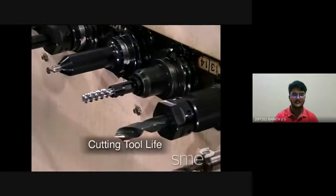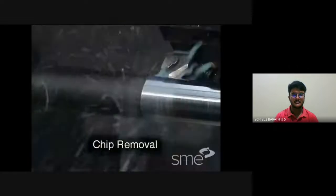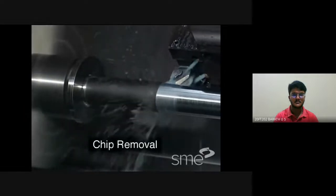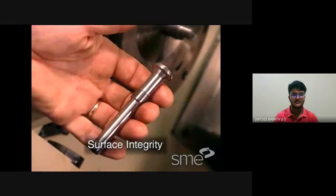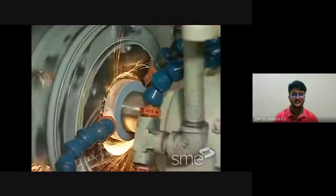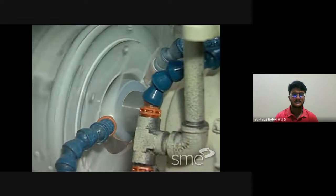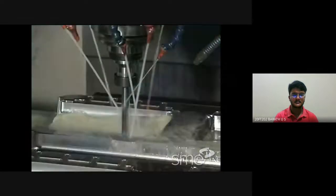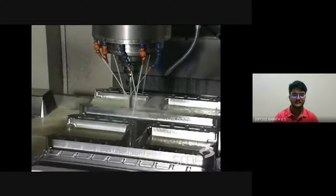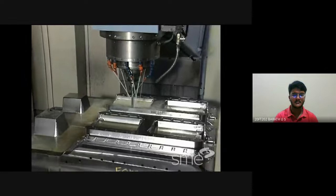The life of the cutting tool is directly affected by the type of cutting fluid and application process used. The faster the chip leaves the cutting zone, the longer the tool life, and the better the surface integrity will be. Surface integrity refers to the quality of the material after machining. How well the fluid reduces friction and carries away heat can have a major effect on the surface integrity of the piece part. Because of the heat and stress generated by some cutting processes, the material may be altered chemically, physically, or experience electrical and magnetic changes.